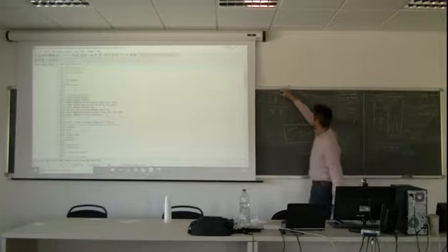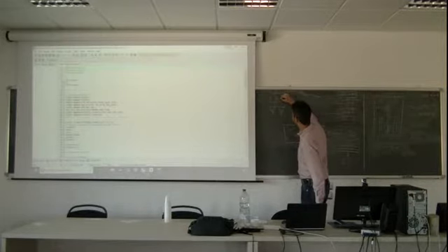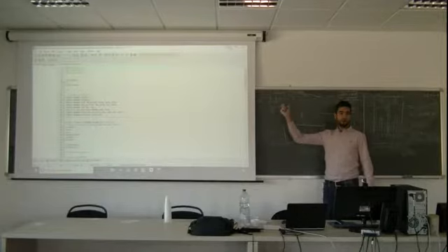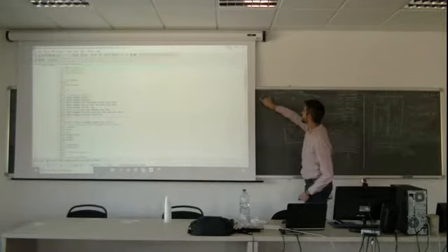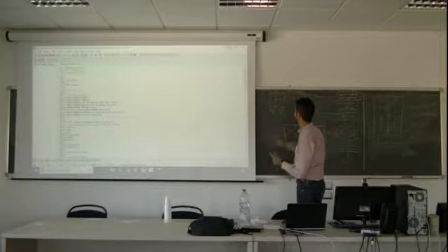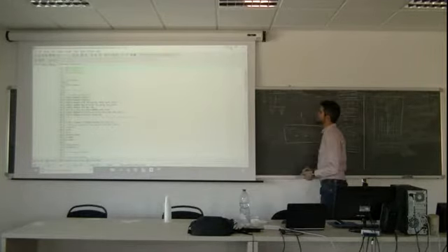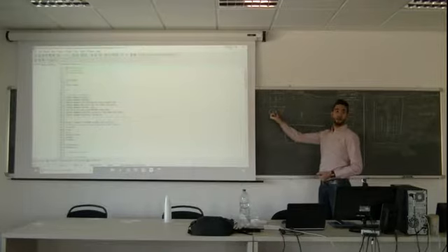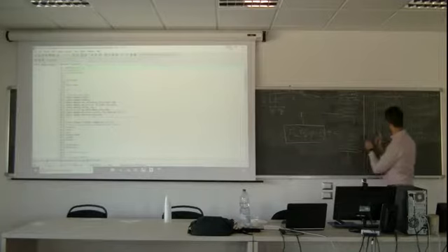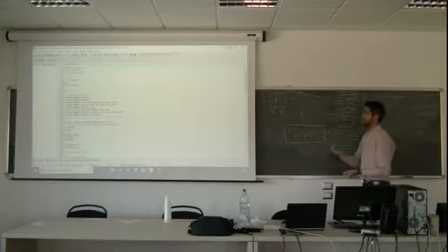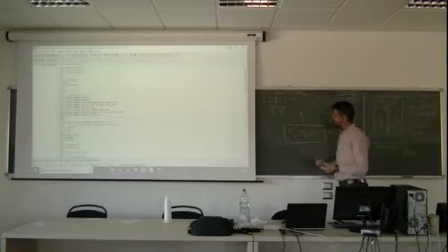This is my node P equal to n. The volume and the distances between, this is closer. This is delta x1 divided by 2. This is delta x2 divided by 2. Because we have different grid size from one side to another. Yes? Okay, let's apply energy conservation.